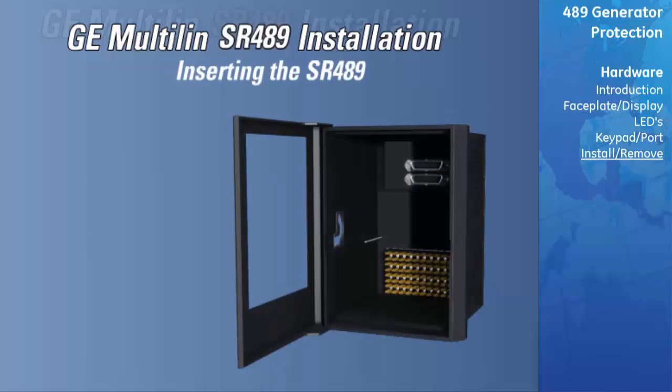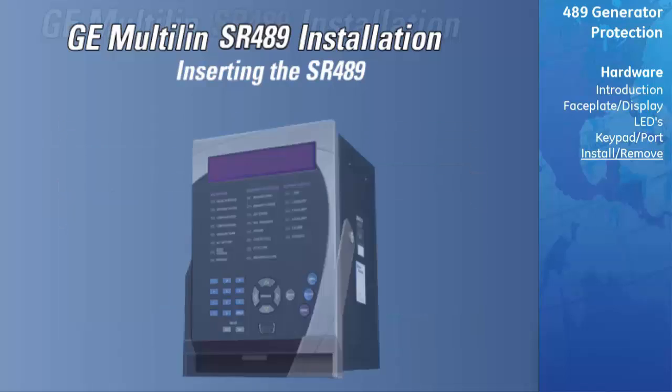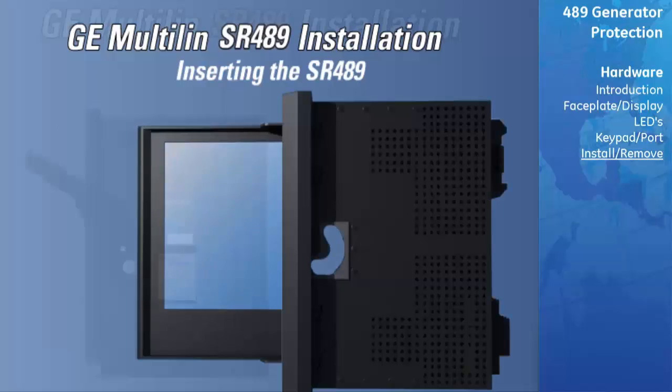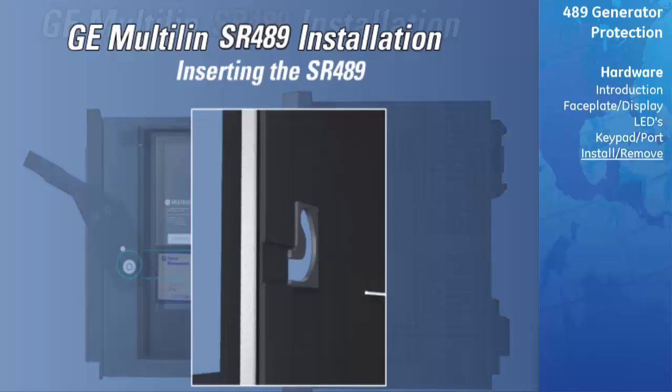If an attempt is made to install a unit into a non-matching case, the mechanical key will prevent full insertion of the unit. Do not apply strong force in the following step, or damage may result. Raise the locking handle to the highest position. Hold the unit in front of the case and align the rolling guide pins near the hinges of the locking handle with the guide slots on either side of the case.